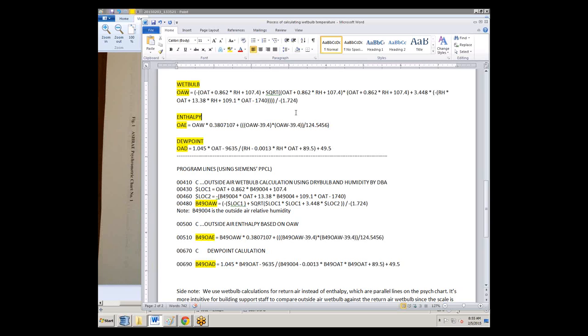One of the things we have to make sure of is that if this wasn't reading accurately and we switch into free cooling mode and can't provide the chilled water expected, then the chilled water temperature itself would be high enough to want the chiller to come back on, and we obviously want to avoid cycling the chiller on and off.